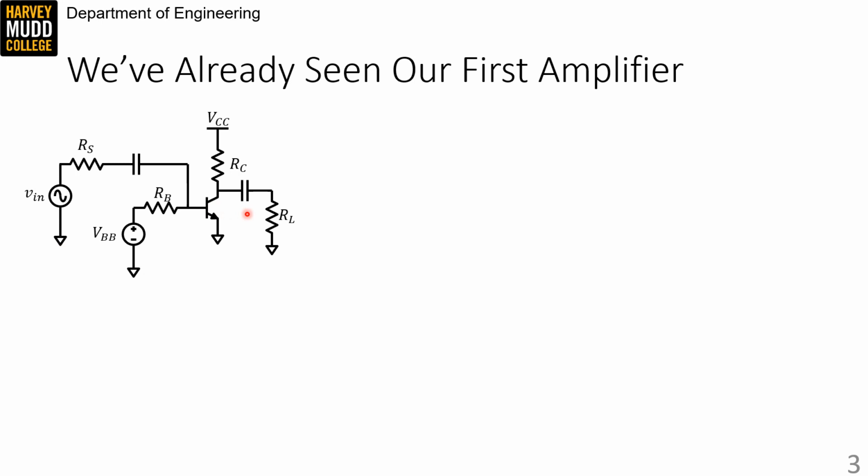Connecting a series capacitor to a signal this way is called AC coupling, because only high frequency signals can pass through the capacitor. The capacitor will have infinite impedance for DC signals, acting like an open circuit, and low impedance for high frequency signals, acting like a short.